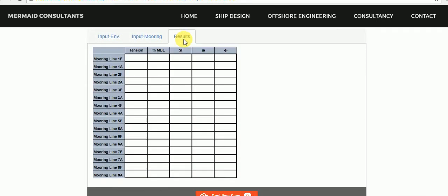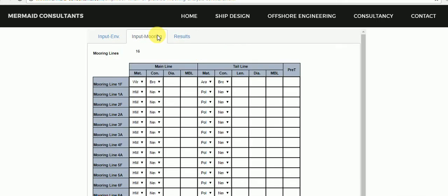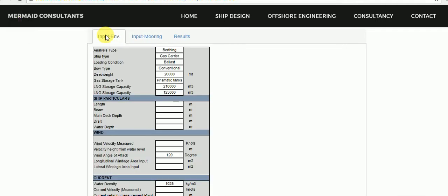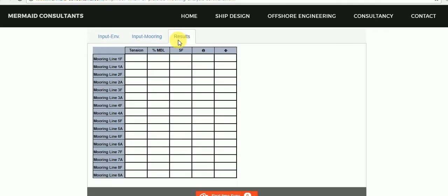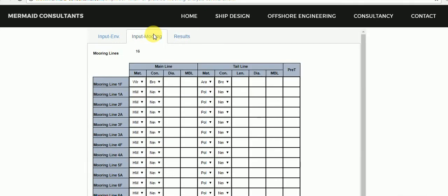Shipmoor has provision for input of initial and final draft and trim conditions and times. It also has provision for tide tables and local correction factors and even for tidal currents. Line tending requirements can be checked in future arrangement. At different times it will show line's tension level and will notify if there is any possibility of tension limit excursion.